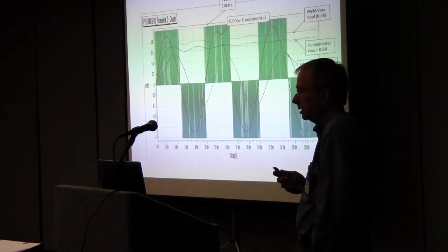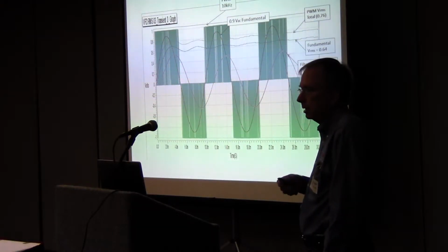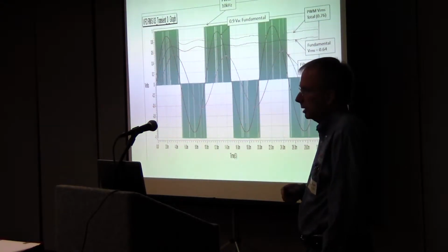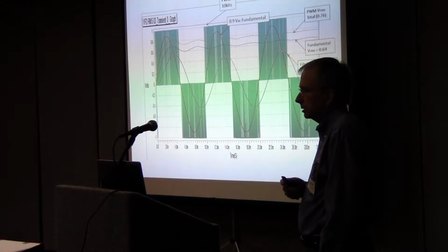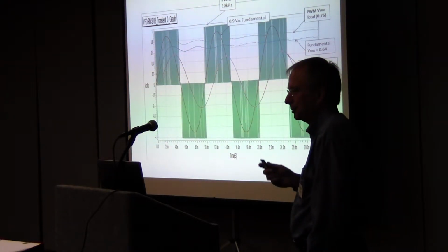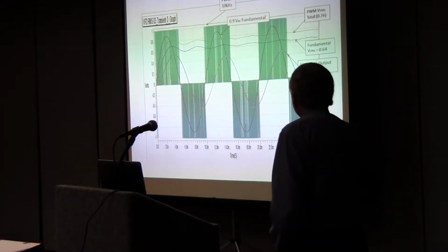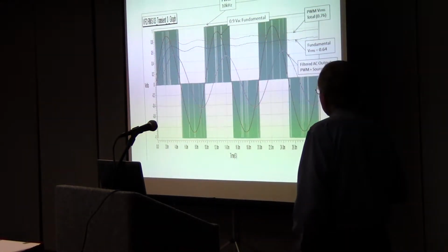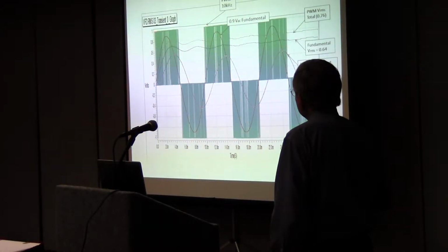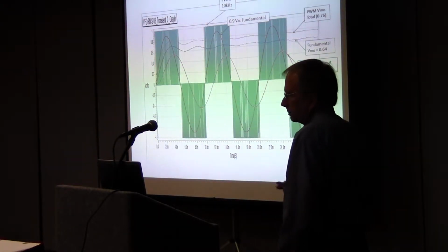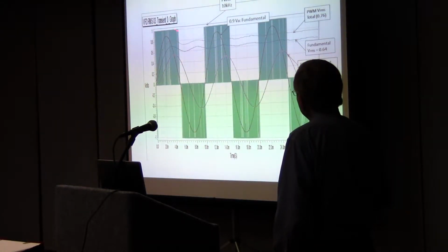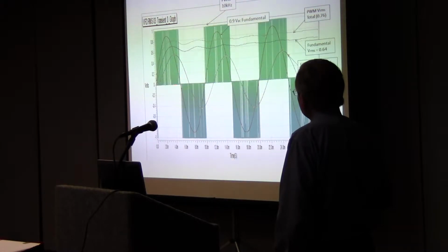Maybe you've done this, but you can capture waveforms and things with some of the scopes and things that you have available to you today. Read that into Excel and do your analysis in Excel. Kind of proof that what you thought should work does actually work. But what I wanted to show on this is this is the PWM. It basically switches between the plus voltage, and we just chose 1 volt to make the analysis simple. But it basically switches between plus 1 volt and minus 1 volt and 0.